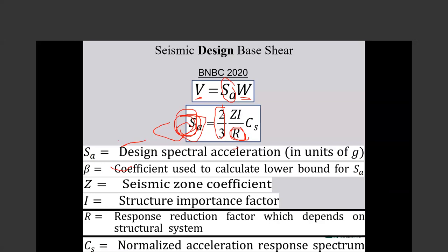Okay, now we did a good job. We reduced the strength, and now we are sure that in the design level earthquake, the building will get damaged. For sure, because our estimation is R times that will impose to the building. But we put the strength, the capacity, at 1/4 of the demand. So it will get damaged.